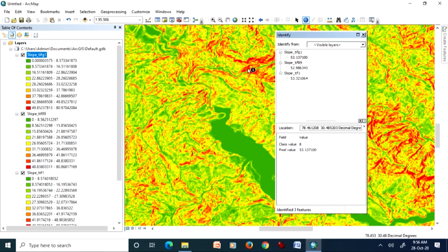Now let me choose another area which is not a very highly sloped area. Here you would see a large difference: the geodesic method with Z factor 1 gives 4.46, whereas the correct Z factor gives 4.2, and the Z factor 1 planar method is giving 4.26.